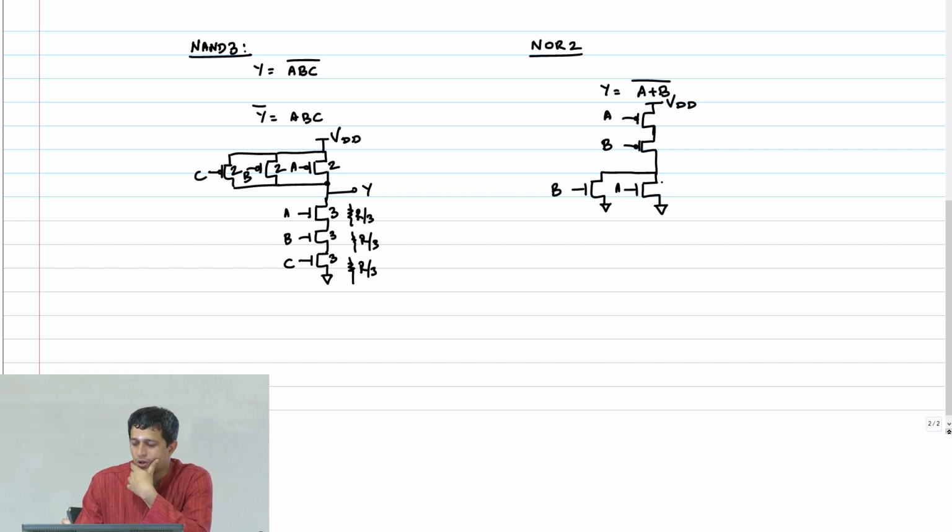Circuit. So what should the NMOS transistor size be now? 1, because I have a parallel stack now. Worst case is only one NMOS transistor turns on, it is 1, okay.